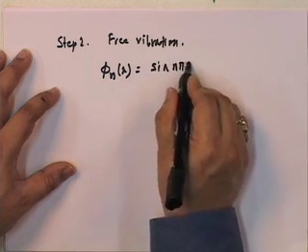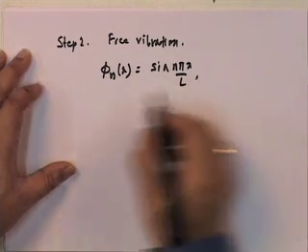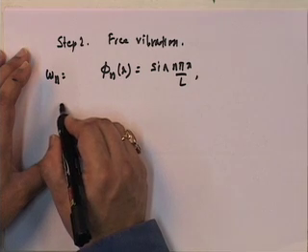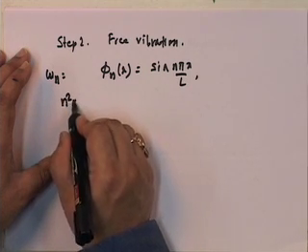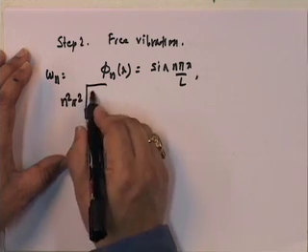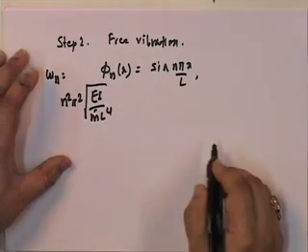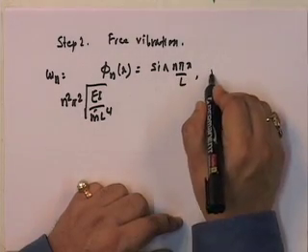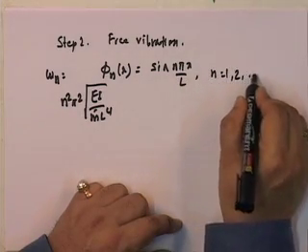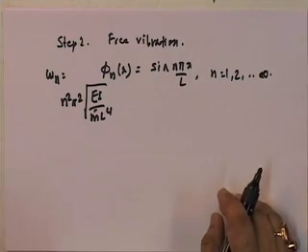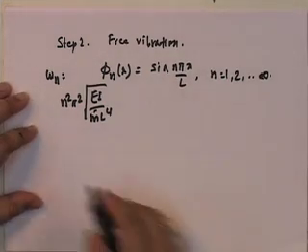It is sine n pi x over L, and omega n is equal to n squared pi squared times the square root of E I upon m bar L fourth, for n going from 1 to infinity. So, we have done the free vibration. I have already done it before, so there is no need.